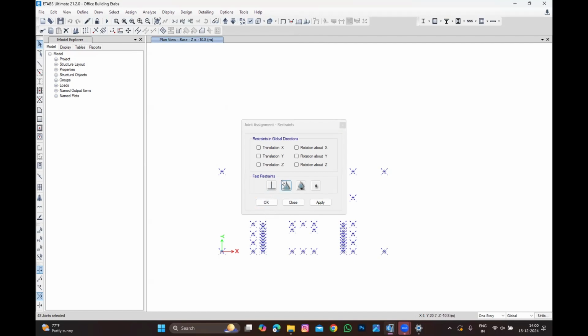What you're going to use is either fixed or pinned. Since it is a high-rise building, you know that it will be either raft foundation or pile foundation. Isolated foundation is only for G plus 1 villa, G plus 2, where the soil is good. You'll go for isolated foundation, and so you'll go for pinned joint, simply supported, because you don't want to increase the foundation size.